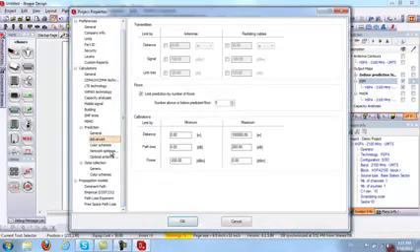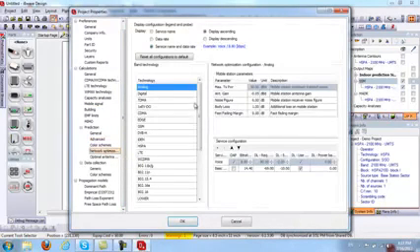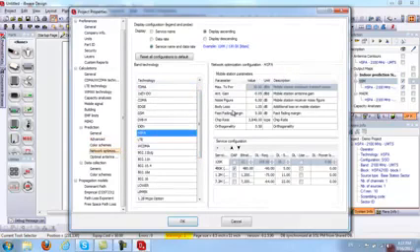So next, again, under network optimization, this is where you can select your technology. Let's do HSPA for now. And on the right side, you have the mobile station parameters, and these will allow you to set the mobile station transmit power, antenna gains, receiver noise, and additional loss. Under service configuration, this is where you can add the different services and specify the requirements per service, like the downlink required power and SNIR, which are taken into consideration when running a data rate map.